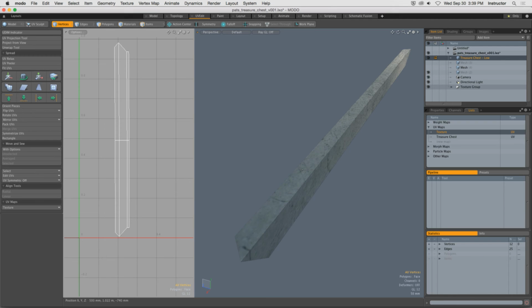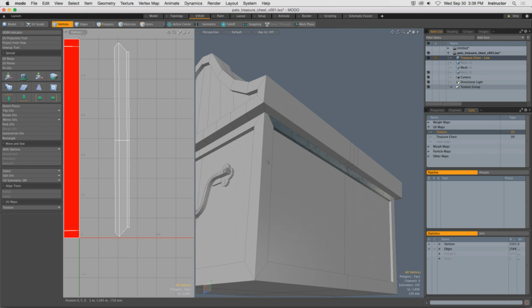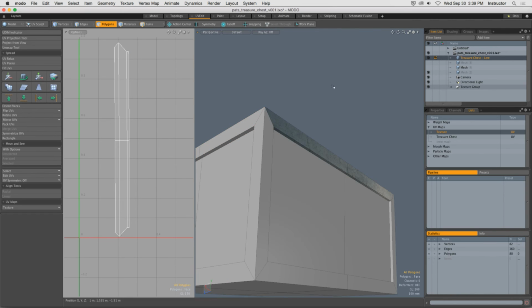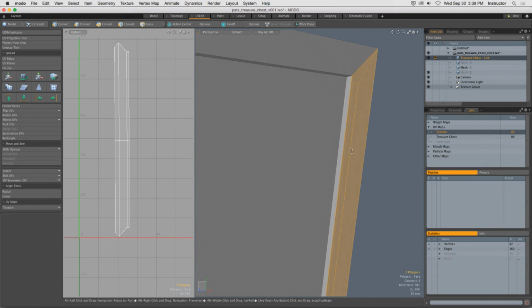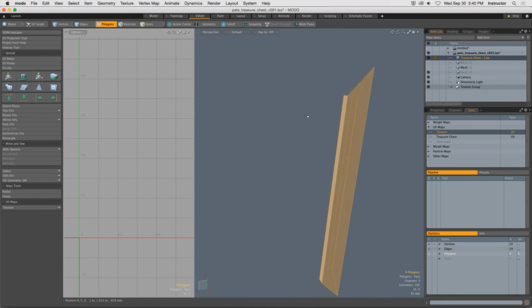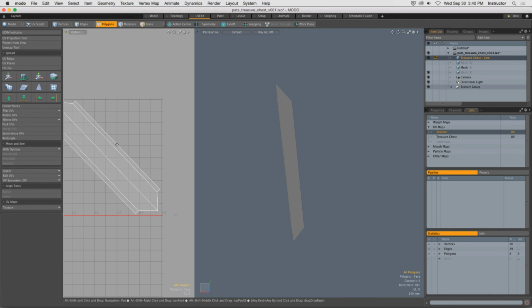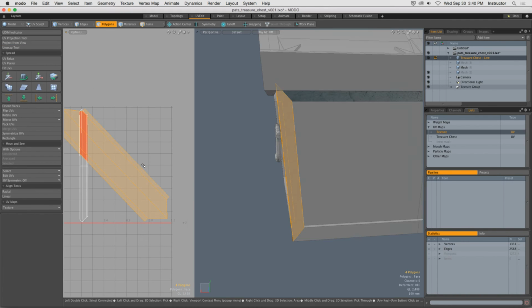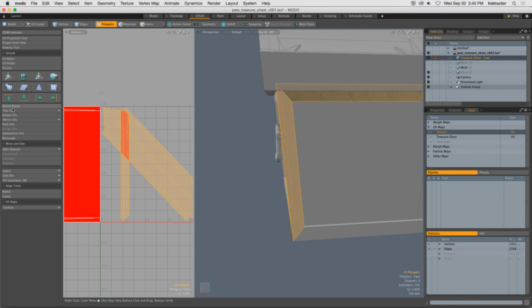Let's do another pillar of my metal frame to help illustrate this. I'll unhide the rest of my mesh. And I'm going to work with this guy. So I want to try to keep this all one piece. Shift H. I'll run UV unwrap. It's going to be initial planar projection. There we go. Awesome. Wonderful. And I'm going to grab that one and that one. I'm going to pack them. There we go.